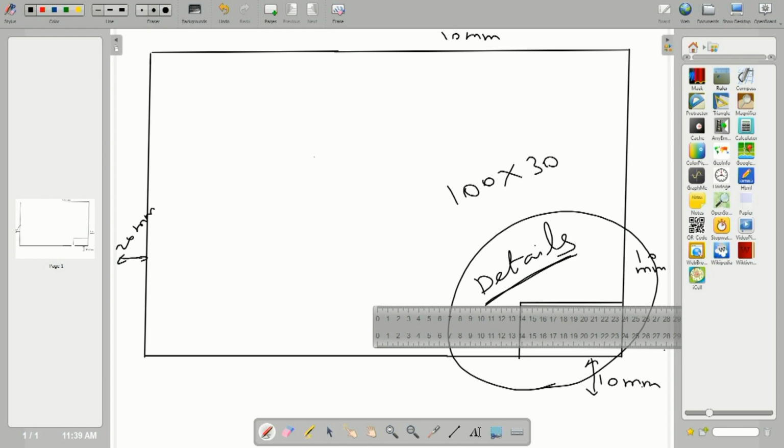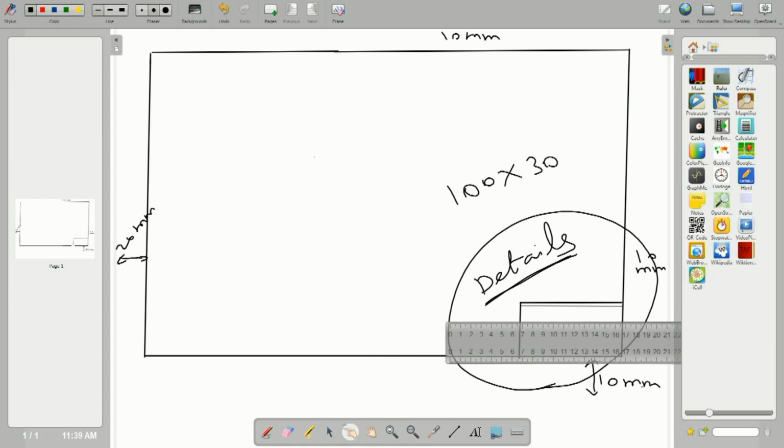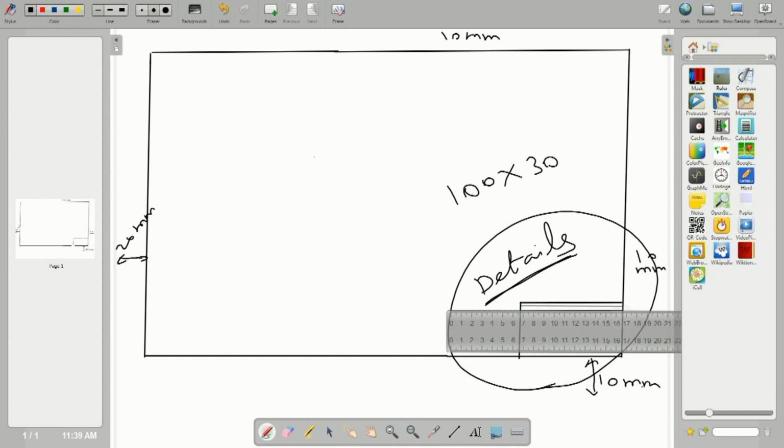Again, approximately 2.5 mm, not exactly 2.5 mm, then 2.5 mm below, that is 2 mm, 2 mm, 6 mm height. So we have chosen 6 mm height normally in this. It is approximate, not exact, but in any layout this should be fixed, that is the printed one. Then this is also a thin line. Then to divide the other particulars, we have to choose a thick line.